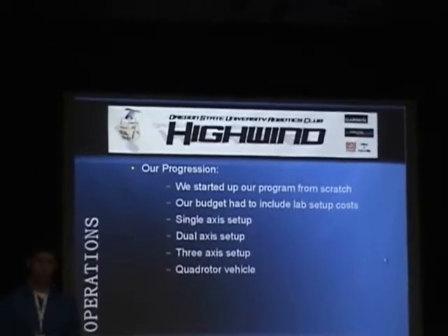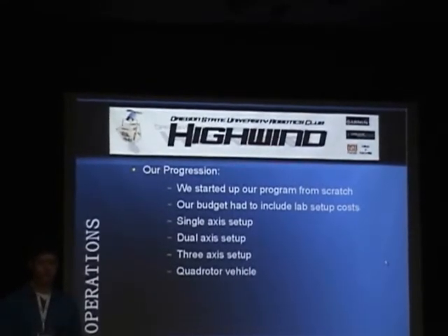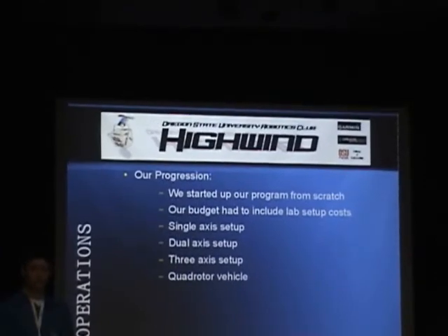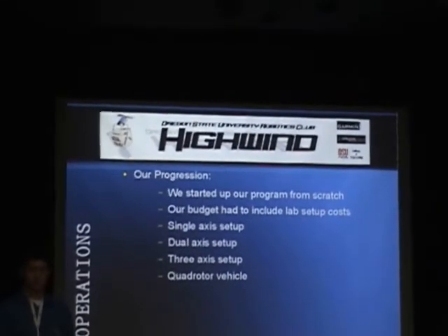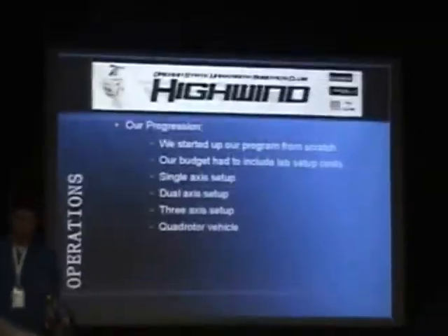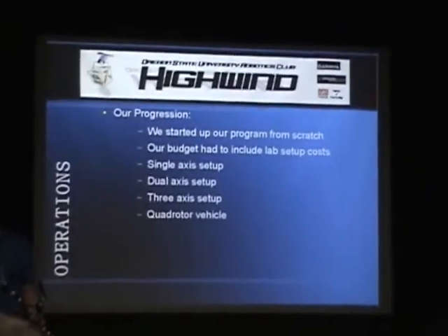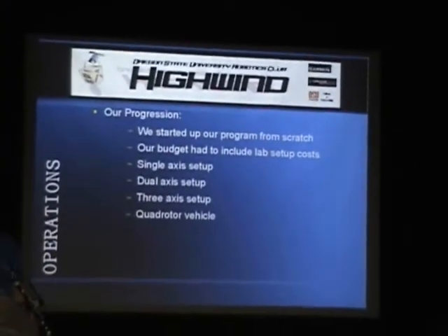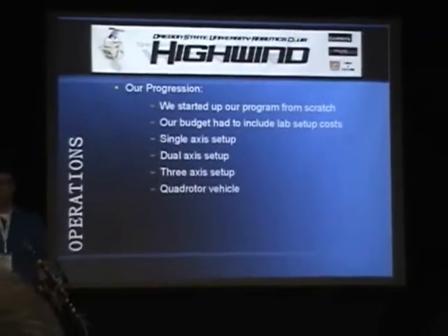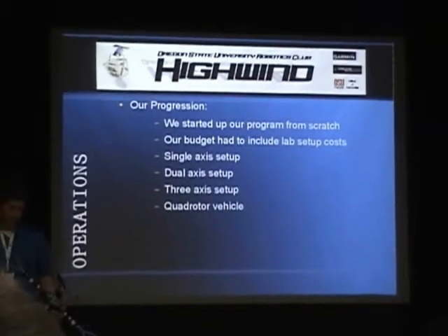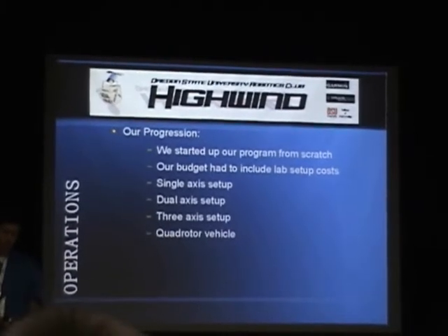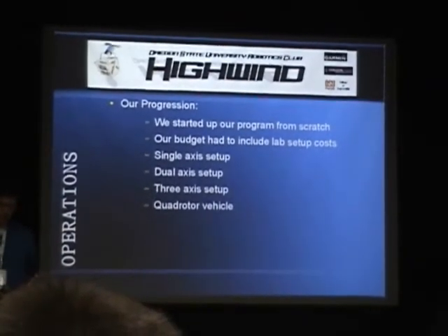but we started very basic, and this was one point that we wanted to bring out: we started with just a teeter-totter with 2 motors on it, put the IMU on it, and got a good handle on what a PID loop is, and then we cut and pasted it into two axes and had a 3-axis setup, and then we progressed from that up to our vehicle. So going in stages really helped our development and improved our ability to nail down errors at later points, because we didn't have to troubleshoot the entire vehicle all at once.